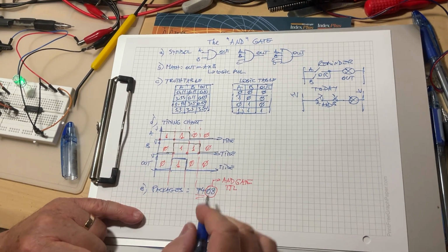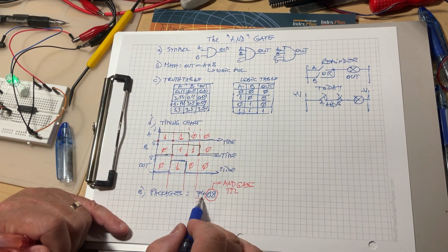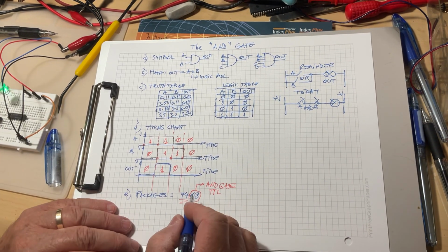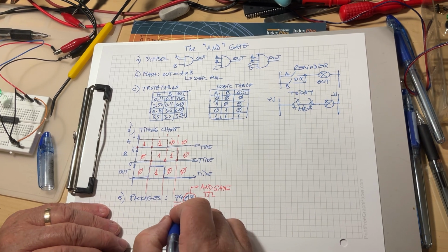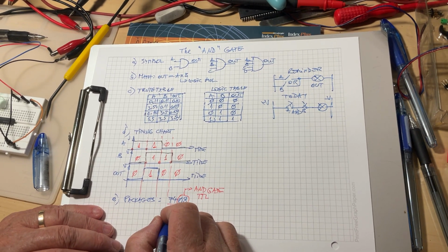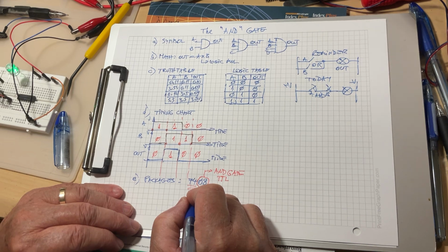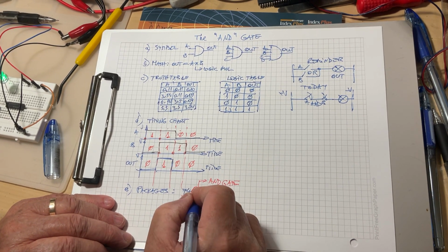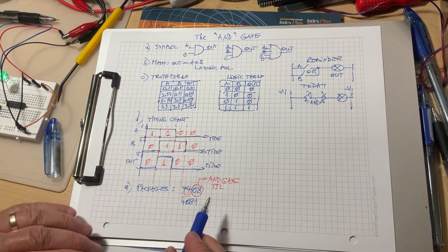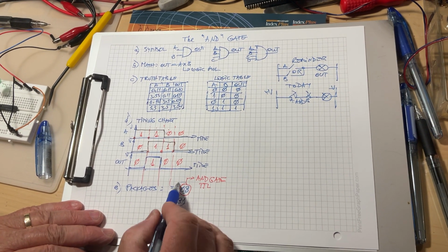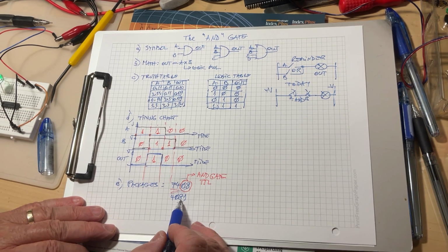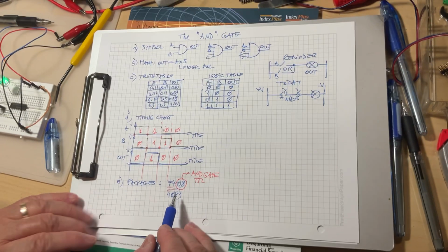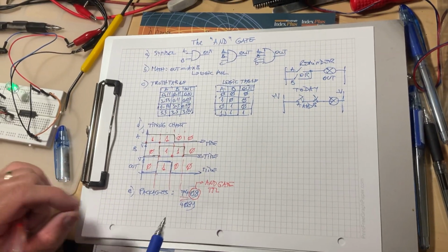And there are variations of this. It may be 74LS, 74ALS, 74HC, 74HCT. And in CMOS, in the first generation of the CMOS, I'm going to give you the equivalent one, is 4081. This is also an AND gate, like this one. However, not only the voltages may be different for the two kinds of packages, as in another video, but also the packages are not interchangeable because the way the gates are arranged inside is not the same.